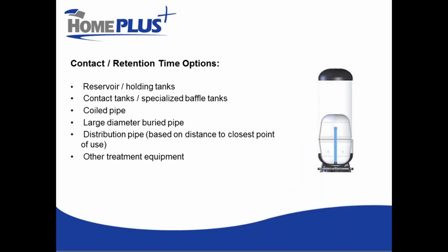Contact time can be provided by many, many different options. On the previous screen, I showed a couple of baffle tanks in series, but this could be a holding tank, a reservoir. It could be just coiled pipe buried in the ground. It could be a large diameter section of pipe buried in the ground as well. Could even be the distribution pipe.